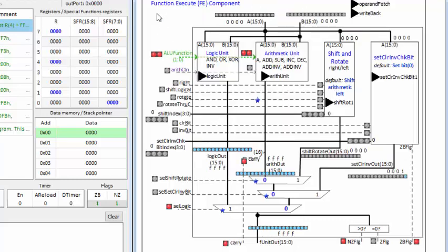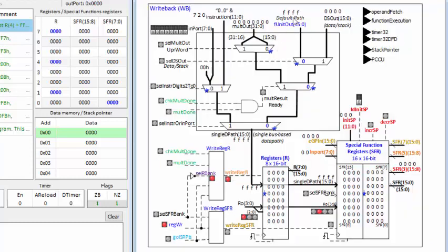So I can go back to the function execution unit, and then into write back, which takes the result FFFF through here. Look at the blue stars, all of the active data path through to the register. So this detail has not been shown yet, but it's the default data path from F unit out to the register bank.